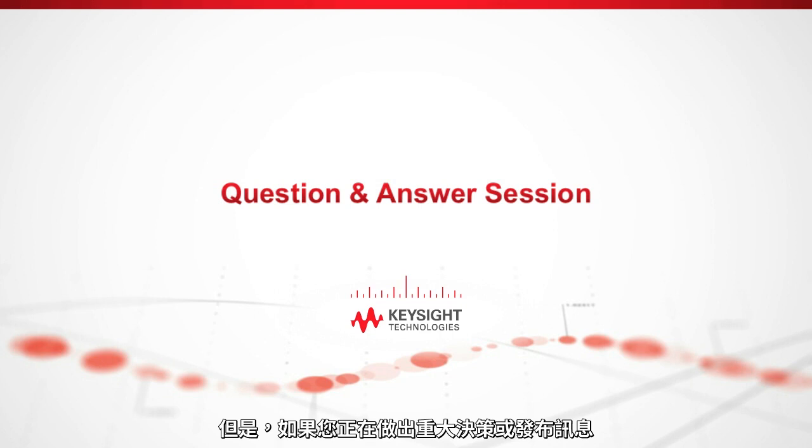Those are things that you can do without calibrating and still get valuable information. However, if you're making big decisions or publishing data, I'd recommend calibrating right before the measurement. Frankly, any measurement that I make, I calibrate right before it. I normally end up spending one day in the lab, and I'll calibrate in the morning. If no one has touched my setup and my cables are taped down, I can come back in the afternoon and make good measurements from that calibration. But if I don't know if someone has borrowed some cables or moved the device under test and created some phase error by bending a cable, I'd recalibrate. And as I mentioned, with the eCal, the calibration is very fast, even for these multi-port systems. So why spend all the time and effort to make a measurement if you're not going to be able to use that golden nugget and call it accurate for a long time?